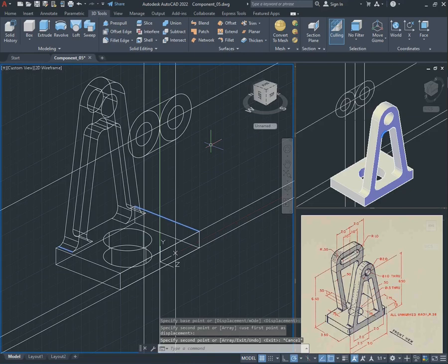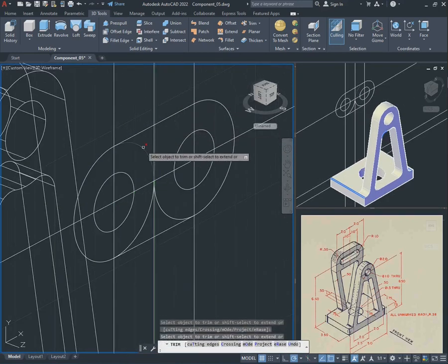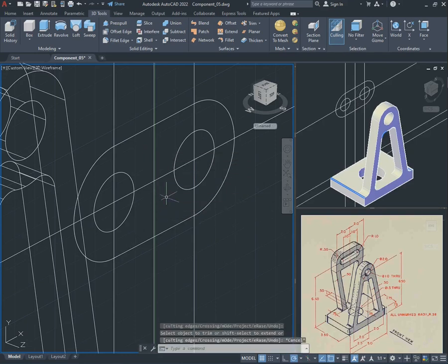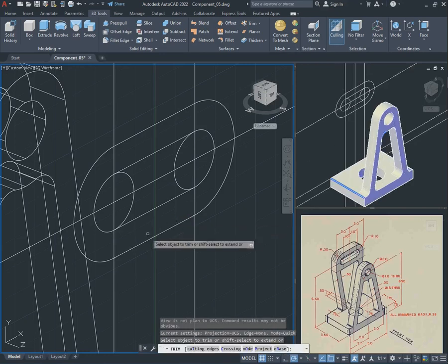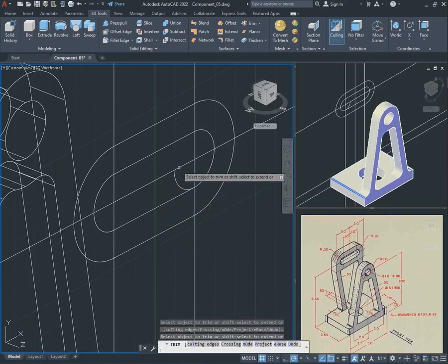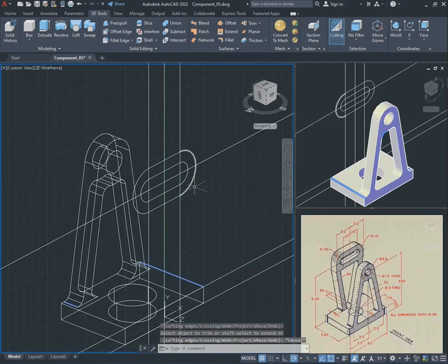So what else? I'm going to use the trim tool to trim this thing, and then copy the P line that we have here, paste it here, and this quadrant as well. Then trim the excess curve there. So we have that. So what else do we need for this side of the component? We're going to create the leg. It's like the supporting leg.